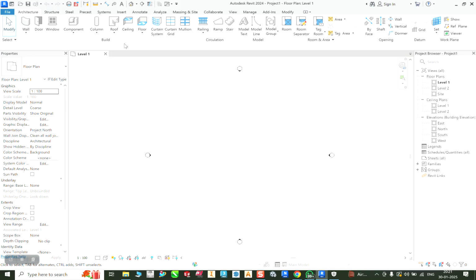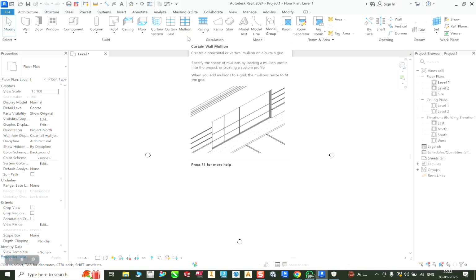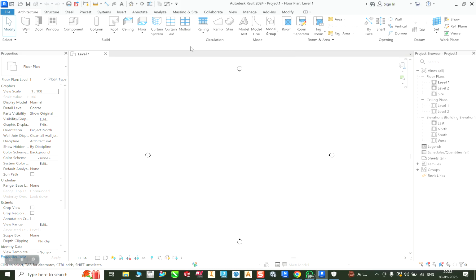When you are working in the architectural module, you are going to do only modeling. There is no part for reinforcement or the structural part. It's not going to be there. You are never able to define reinforcement in architectural components. So you can see here these columns and other things; you are not able to assign the reinforcement. That you are only going to do in the structural part.